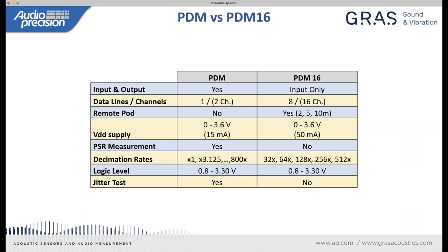For our regular PDM module, there is a line driver accessory, but it makes up for or masks the issues of cable loading. But you do tend to get into some issues with reflections and ringing due to impedance mismatches. So a couple different schemes, but probably the largest issue is just the raw number of input channels you want to measure.